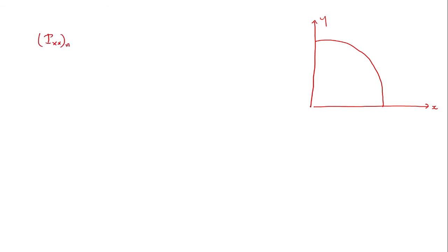So Ixx of A, the area moment of inertia which you had studied in your previous semester, can be given as double integral y square dA. This is the corresponding equation here. Now since this is a question involving a circular area, you can express dA in terms of r theta coordinates rather than the xy coordinates here.